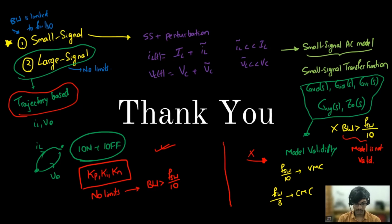the converter reaches from one steady state to another steady state. Just think in this way: in the small signal model, you have considered the KP, KD values you got, and you have given some load transient, and the time it takes to reach that new steady state in the case of small signal, versus the time it takes to reach that new steady state in this large signal case. That is the difference.